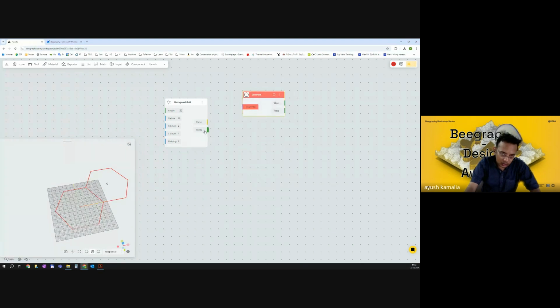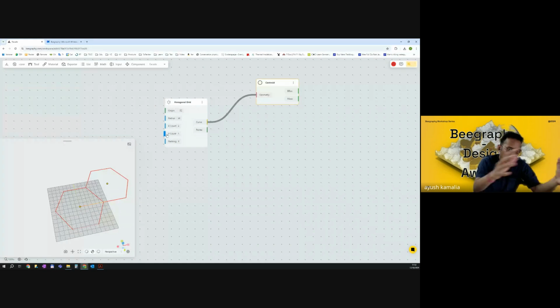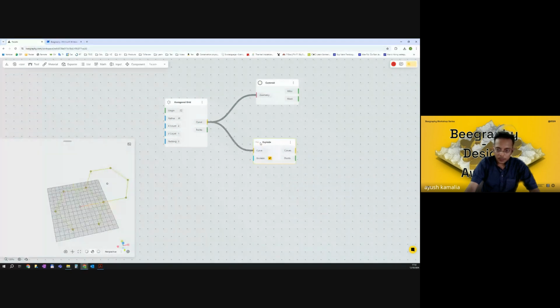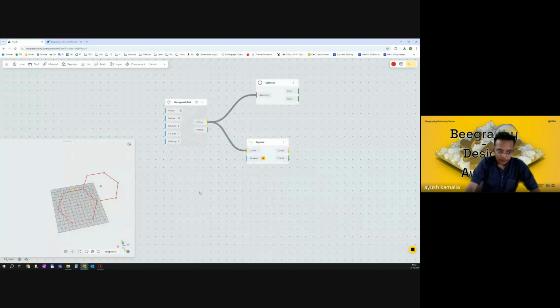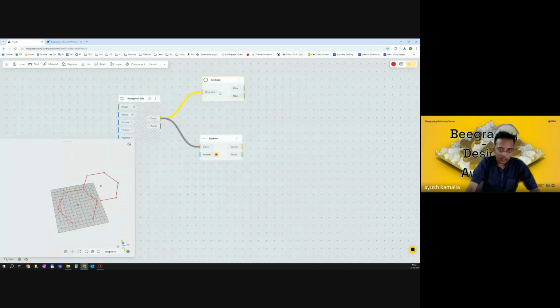We can use the points coming out directly from here, but it is better to use a more parametric approach, so that even if we change this to a facade or a different kind of grid where we do not get the center, we get all of them ready. So we got the center here. And to get the endpoints, we can use a component known as explode. The explode component gives us both points and all the individual curves. We are concerned only about the points. We get them. Now we can hide the base thing. Great, we got all the points.